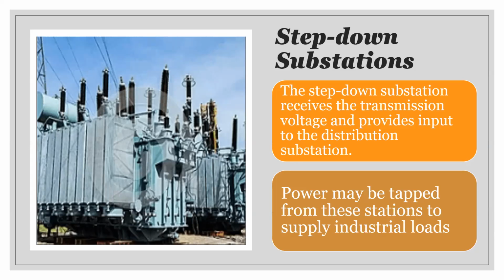You do have transmission along 69, but if we are moving from, say, out by Duane Park, out by 6 miles, yes, sir, that's 138. That's taking some 138 all the way into Trelawny and Manchester. So those are going across country. If you look, you see the lines going over the hills. So that's taking some 138. But in terms of what you'd call local transmission, that's at the 69 level.